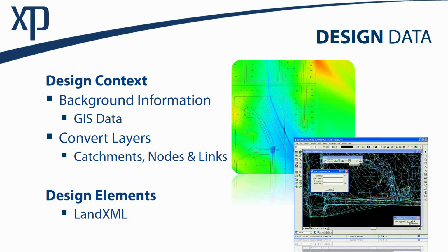I just demonstrated the surface, but pipes and structures can be imported into LandXML with a lot of that information about the rim and the invert, as well as the pipe diameters, already populated. It's saving you time. That preserves the intelligence in that design BIM model, if you will.